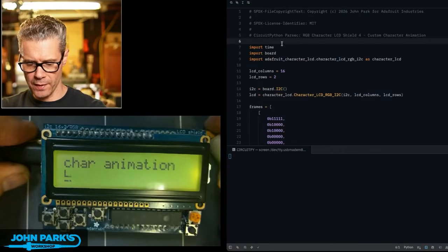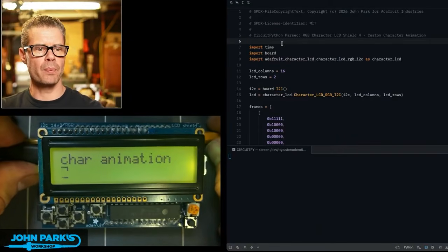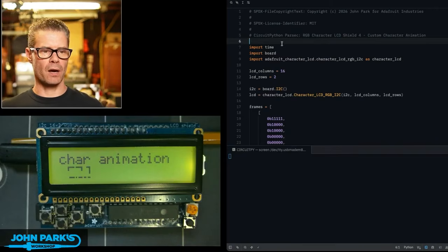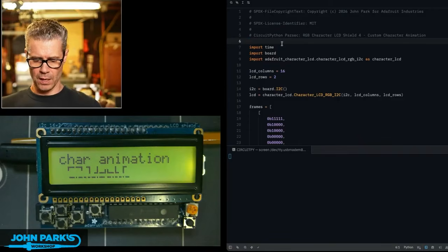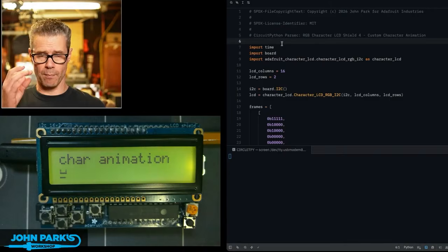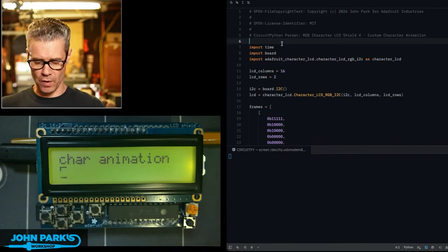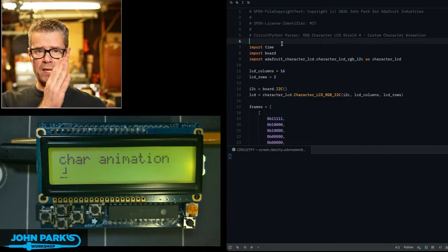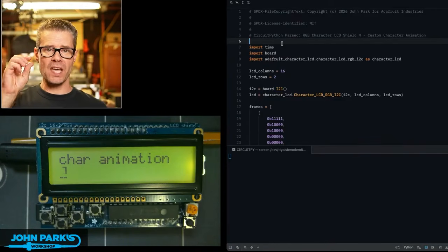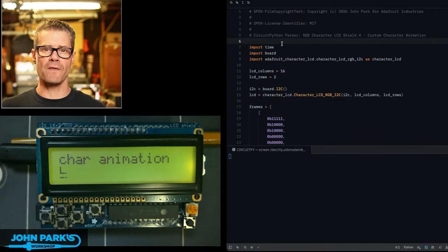And you'll see when this starts up, it's going to loop back around in a second. I'm going to print 8 characters, and these are custom characters, these little glyphs. They don't exist in memory by default, but you can create up to 8 characters and store them in what's called the CG RAM on the chip for this matrix driver. The first thing I'm doing is creating them and displaying them, but then I'm having them loop in the same spot on screen, which gives us the effect through persistence of vision of a little animation. And these are great for little progress bar types of things.